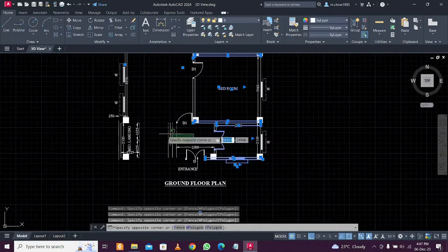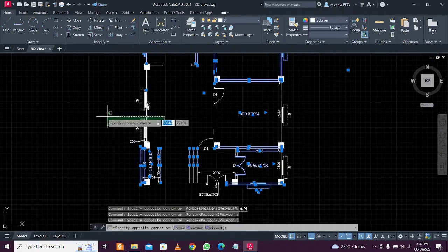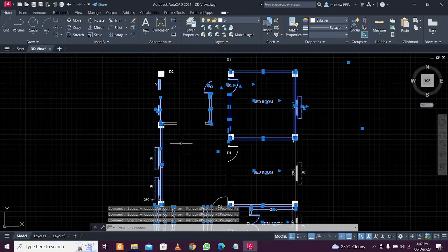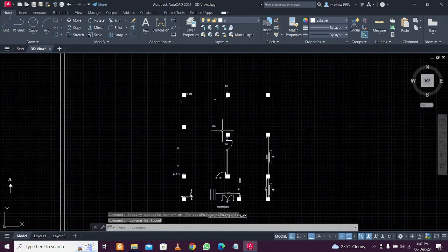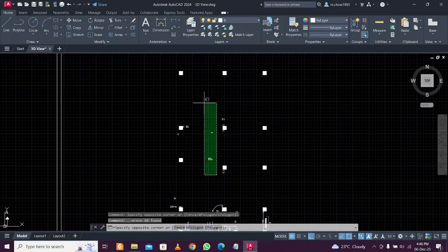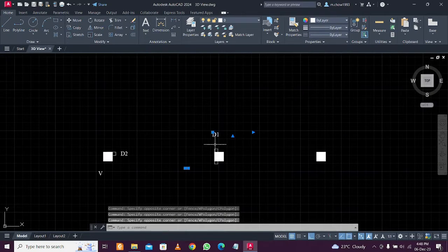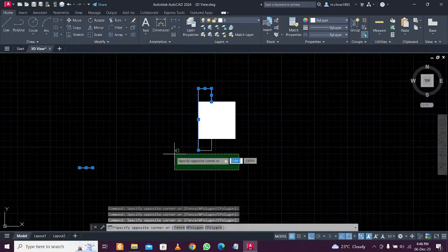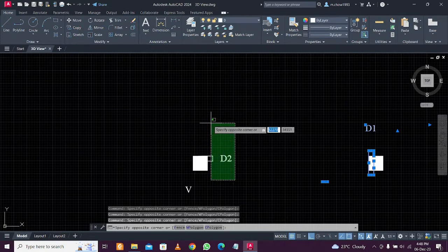We can import the layout from various software results, but they are not accurate. It's best we do the column layout here, because when you take the coordinates, those coordinates might get deflected a little bit, by some centimeters or something.